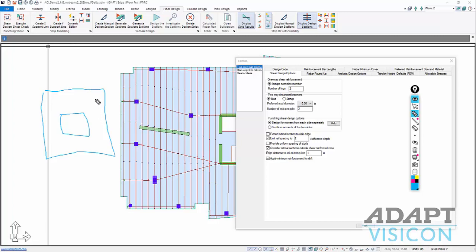That is to say that the actual shear stress is less than the allowable shear stress provided by the concrete. At that point, when no additional reinforcement is required, we'll call this layer 10. We will actually recheck layer 10 at its exact position, but we simply cut off this leg, and we base this now on an octagonal shape. So we recheck this section, again at d/2 from face of column. That's at this layer based on the rectilinear shapes.